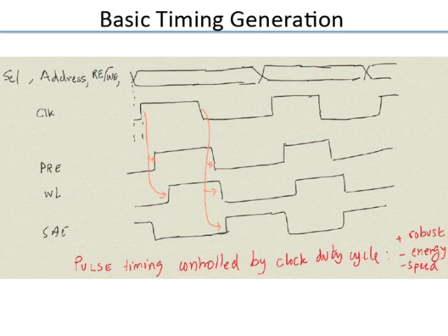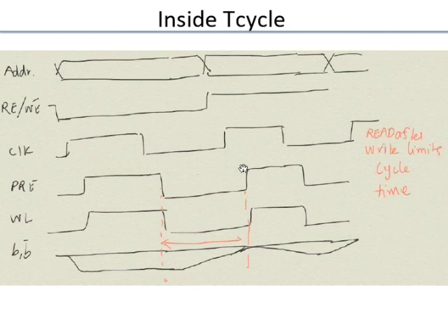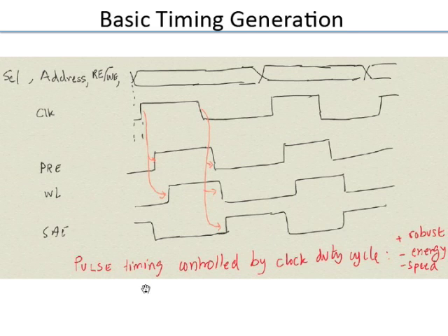So now let's look at one simple way of doing this timing generation. Let's look at the read timing generation. Usually writes are much simpler, because in a write, you're done basically out here. You put the data, and after some time you give enough, whatever you did for the reads will also work for the writes, as far as making sure the writes work. In the reads, the tricky thing is generating these, especially the SRAM signal.